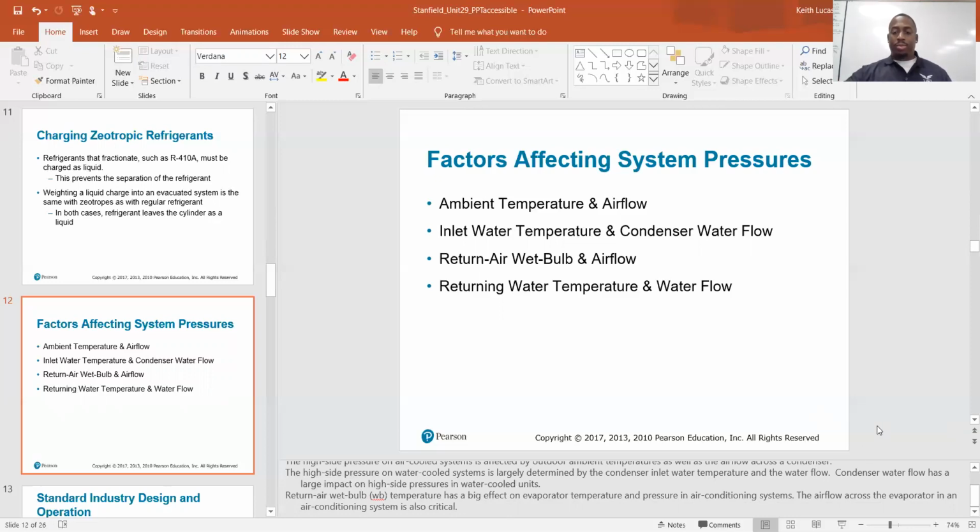And then the airflow across your condenser coil is also extremely important, because at the condenser, that's where we want to reject heat. We want to use the cooler outside air as a means to transfer the heat energy from the refrigerant into the outside air. And then that fan blows that up. When the condenser fan is turning, it's pulling that cooler outside air across it and then blowing the warmer air out of the top. And it can't do so if the condenser coils are clogged up with dirt, or if, I've seen people have plywood and junk in the backyard leaned up against the side of the unit, or even have shrubbery around the unit that's too close and not allowing good enough airflow.